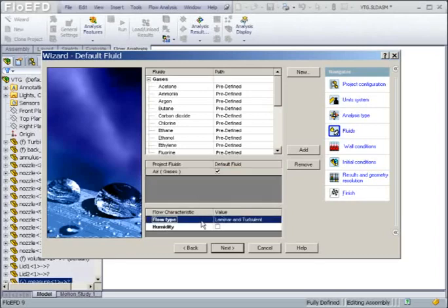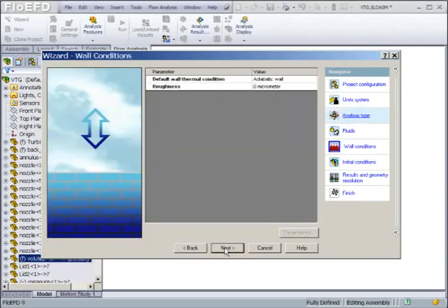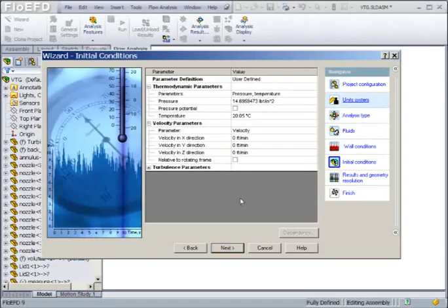You will also notice the flow type is set to laminar and turbulent, so FLOEFD can decide what the flow regime is in various sections of the turbocharger. There is no need to consider additional friction at this point, so we'll leave the solid walls as smooth and just move on to the next step.